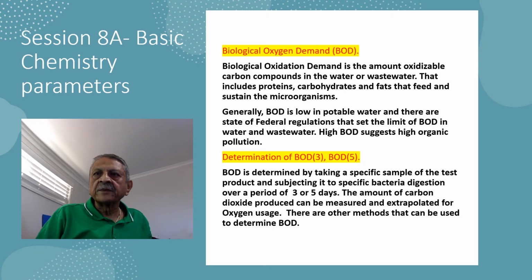So we determine the amount of oxidation by the organic materials, organic bacteria, by the amount of carbon dioxide produced, and then we extrapolate how much oxygen is used. There are other methods that can be used to determine the BOD.